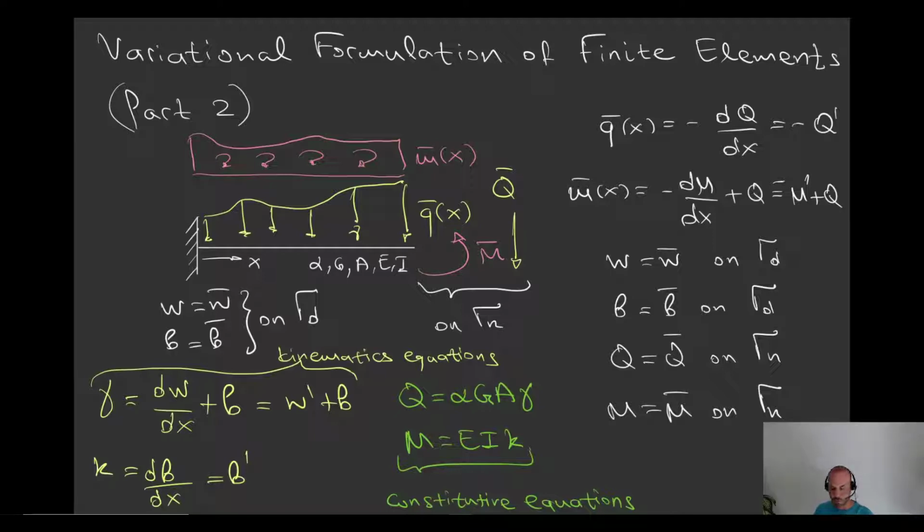And please recall now also that for thin beams, the big issue we had was the so-called transverse shear locking, which was stemming out of the Kirchhoff condition, which tells us that the gamma, so the shear deformation, has to be equal to 0 for thin beams. But in this case, due to the choice of basis functions which were linear for the two-noded linear elements, there we can see that the sum of the derivative of the vertical deflection plus the cross-sectional rotation wasn't possible to be equal to 0.